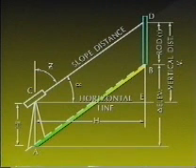The most convenient method used today for trigonometric leveling is with the use of a total station and prism pole. But depending upon the accuracy required, a theodolite and rod employing stadia can be used. The following illustration details the basic concepts of trigonometric leveling.